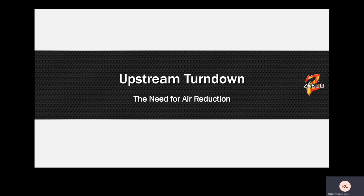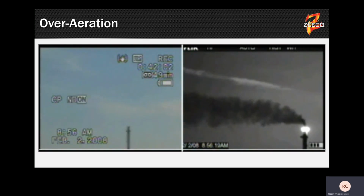And so one of the challenges is upstream industry, so the well site, shale plays. This first video is a picture of a flare that is in operation according to the control system. So the pilots are lit, everything is as it should be according to the control system. But as you can see, in the picture on the left, there is no flame. The one on the right is a FLIR image showing where it's venting.